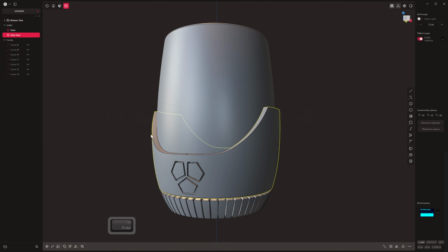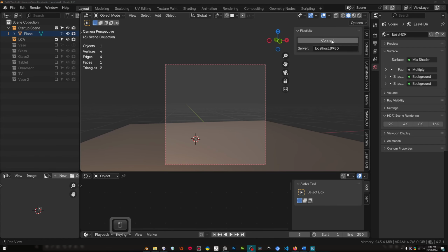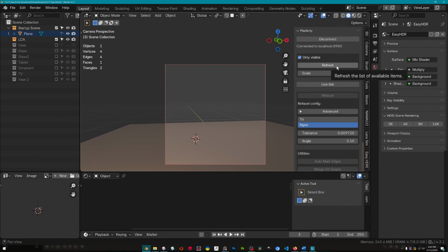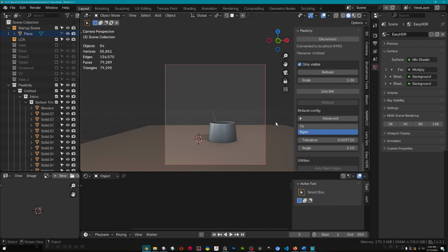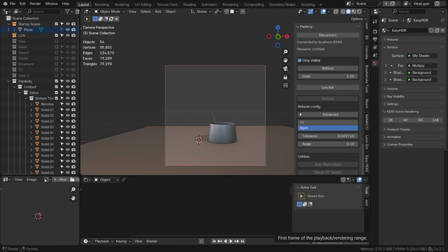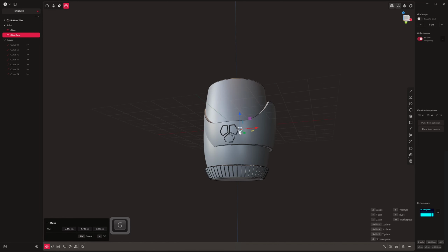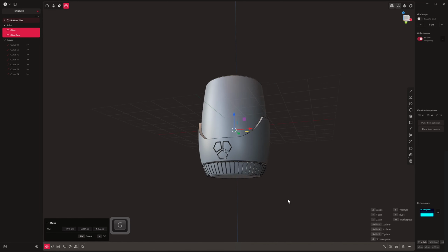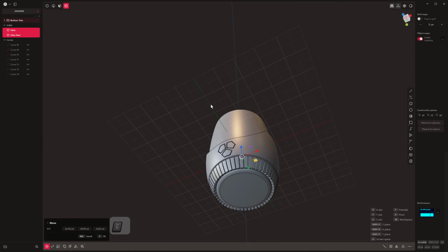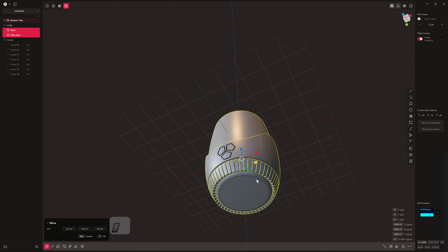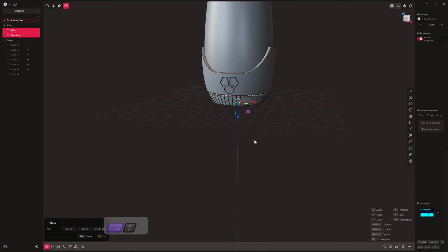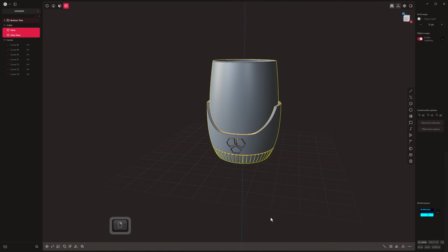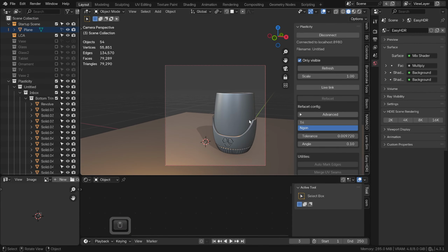Okay, so going over into Blender, we can connect our Plasticity Blender bridge and just refresh our scene, and that is going through the geometry. So what we'll do is we'll go back, and in Plasticity we'll GG everything and hold down Control, and we'll GV to select the pivot as the base, and then G again, hold down Control, and we'll set it to the origin point. Okay, right click to accept. We can refresh that, and it's nice there up on our scene.